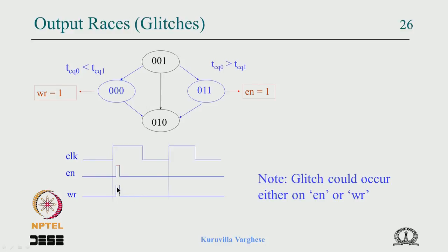Then for a brief duration the write pulse goes high, and if the access time is enough, maybe the address line is floating, or some value is there, the data line is floating, but then something gets latched into some address, and that can corrupt some location. So depending on how fast the memory is, how short the access time is, and so on, this could create a problem.